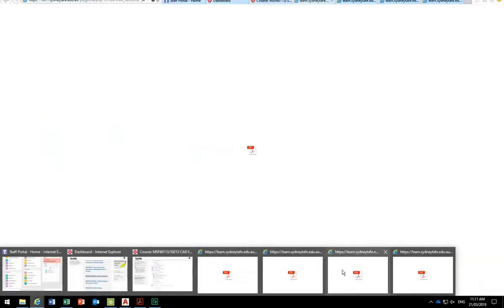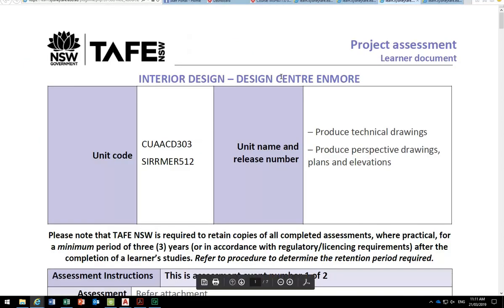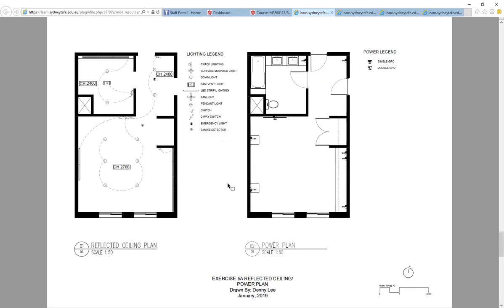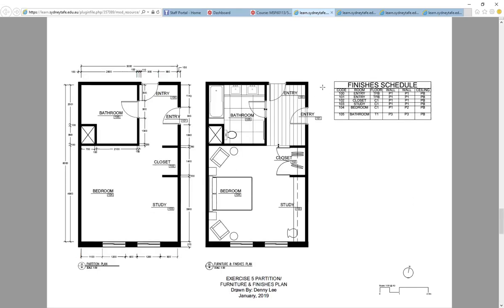And so the only other thing that we need to do afterwards to finish off these pages, apart from maybe looking at the RCPs a little bit, there is one other thing you might have noticed on the cover sheet, on the floor plan page. You've got this table. And I'm going to show you the table tool. There is a tool, of course, in AutoCAD for making tables.